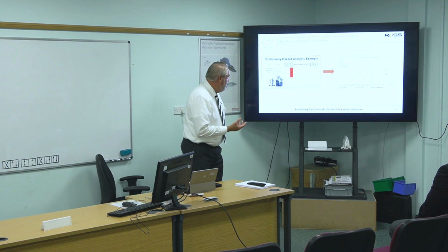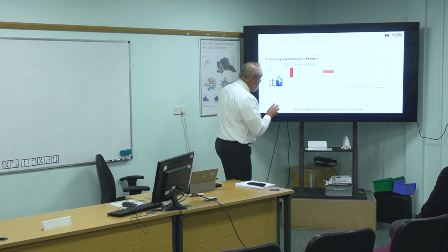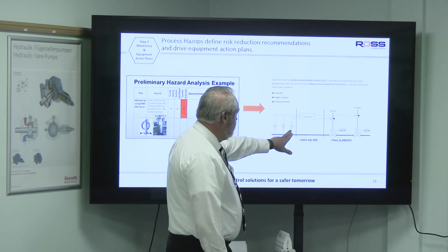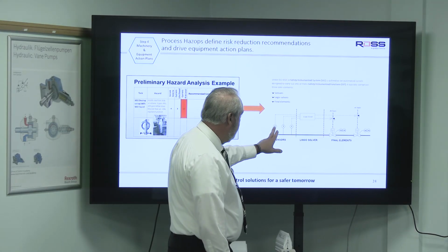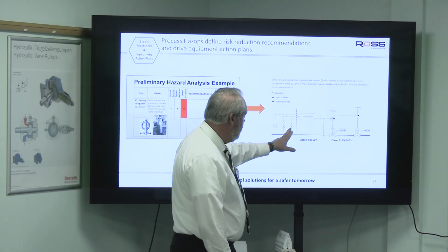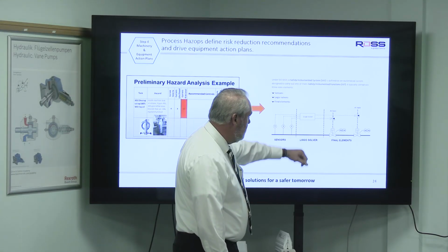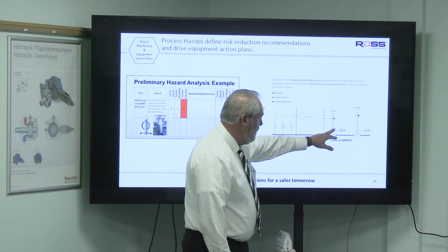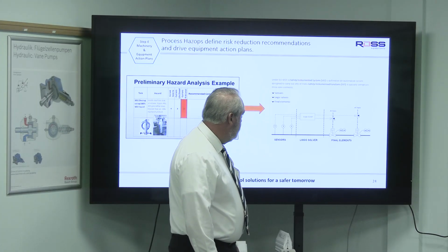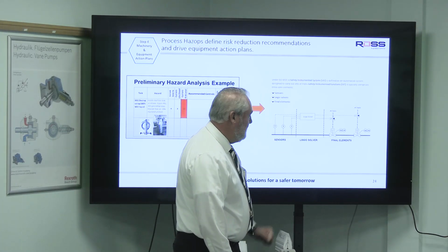And in the world of process, they do things a little bit differently. So if you look here, they have 3 test sensors in the field. These test sensors are going to a logic solver. That logic solver is then driving a valve, and that valve could be pneumatic or hydraulic, depending on what they're doing. But they use like a voting system.